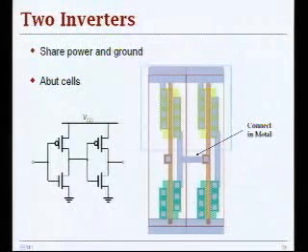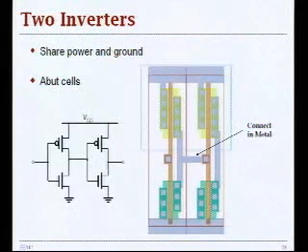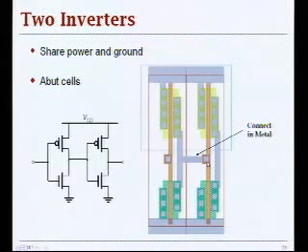So when you have two inverters, you just put their layouts next to each other, and then you connect the output of the first gate to the input of the consecutive gate in metal 1, and you are done. So these are some simple exercises to get yourself familiar.